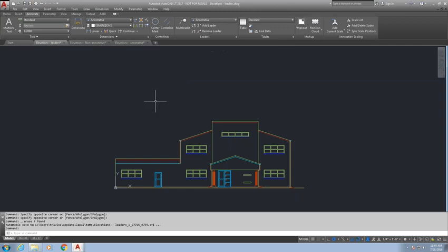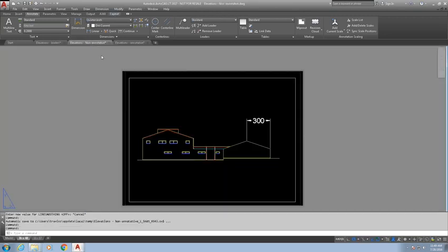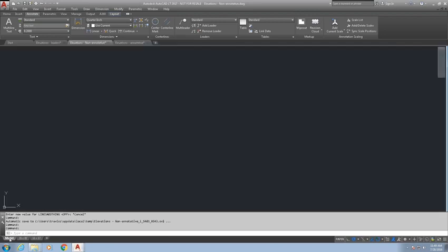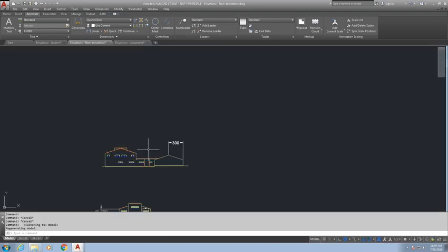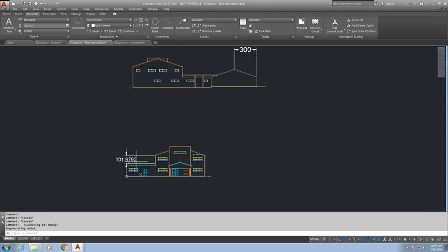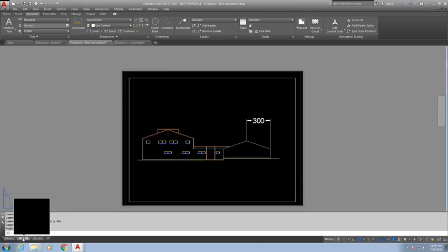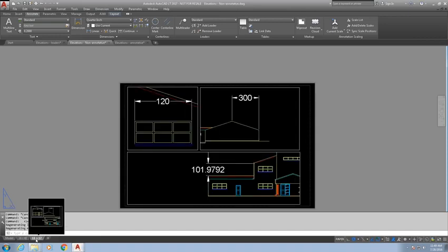So lastly, and very quickly, I'm going to give short shrift to annotative scaling here, but we'll try to cover it. I'm going to show you two comparison drawings, and for the most part, I did my best to make them look identical. So a non-annotative drawing, here is an example. I've got a model, the same old house drawing, and on the model at various points I've drawn dimensions. As you can see down in my layout tabs, I've got one with a paper size of 36 by 48 and another with a paper size of 11 by 17.